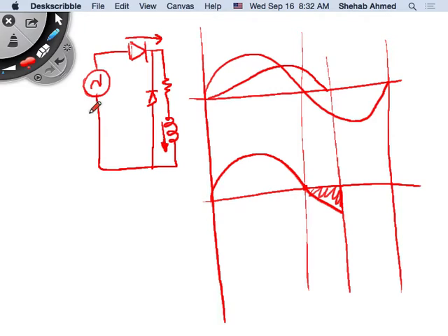And now I'm in the negative half cycle. So this is positive, this is negative. Before I put this diode, this voltage here, the opposing voltage that flipped in the negative direction, what it was doing was decreasing the current inside my inductance. It was decreasing the current through the inductor, right?